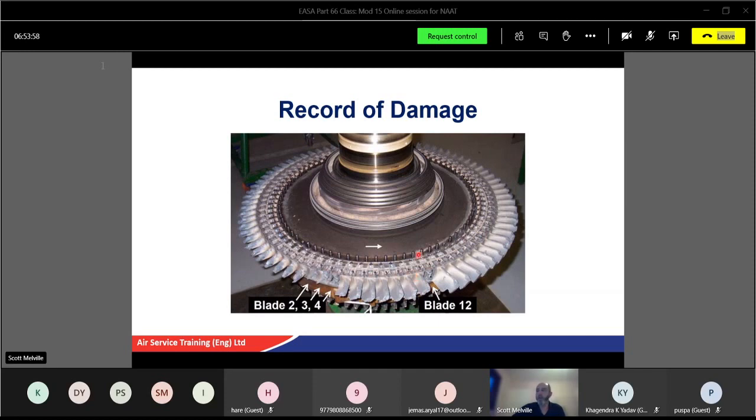I'll try and maybe find information for that. On the turbine, there's a disc. You can actually see the seals, the air seals, around there. And there's the main face of the shaft. So by the size of that, I would say that's an HP turbine. Look at the size of it. But yeah, it's broken. I'm not going to run that one again.